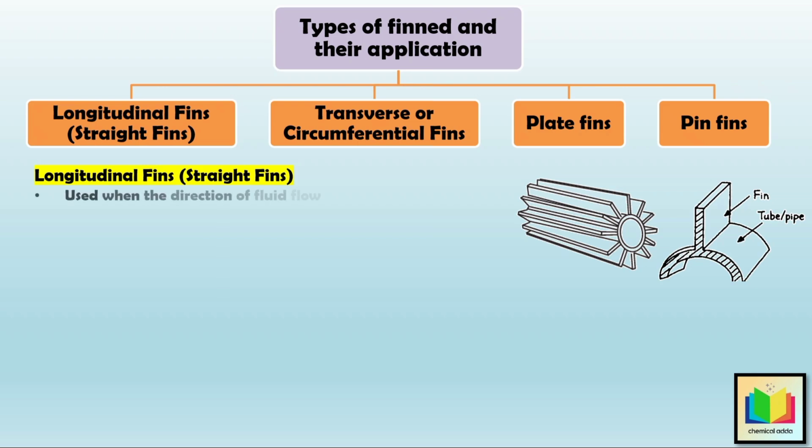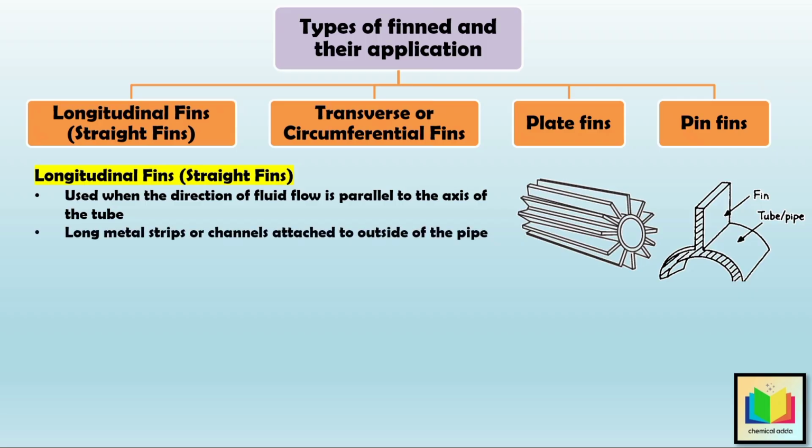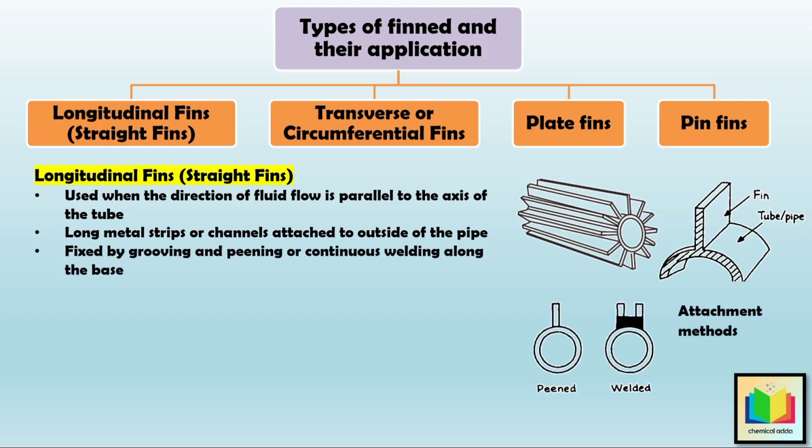So, these fins are used when the direction of fluid flow is parallel to the axis of the tube. And hence, in this case, long metal strips or channels are attached to the outside of the pipe. Then, they can be fixed by grooving and peening the tube or by continuous welding along the base.